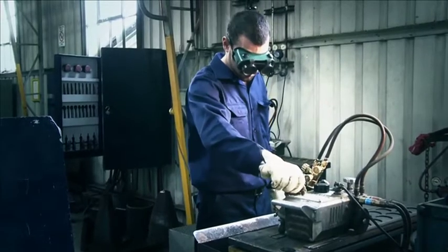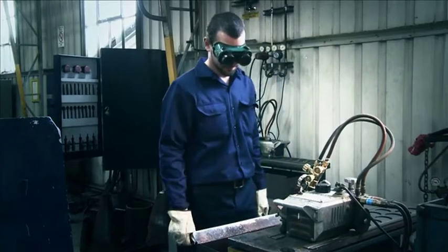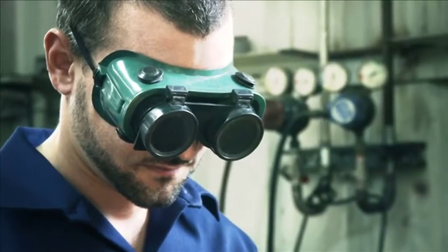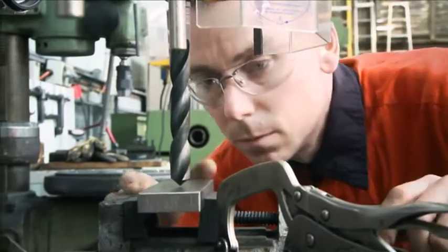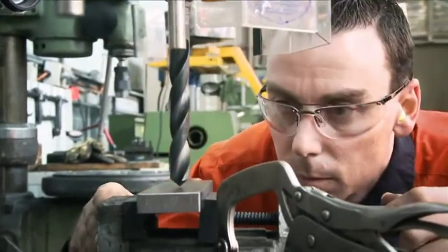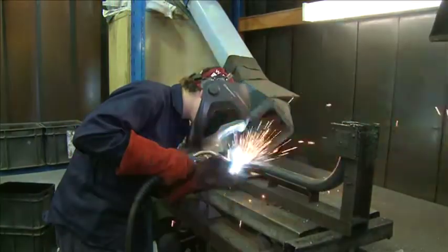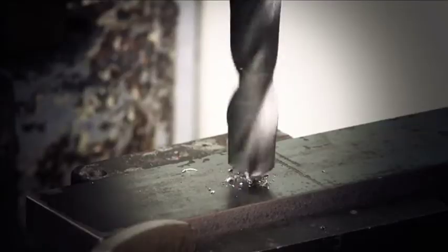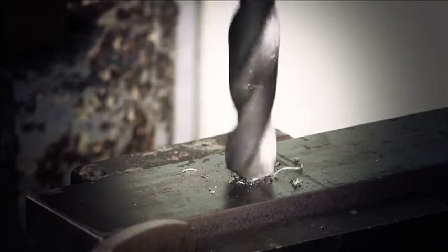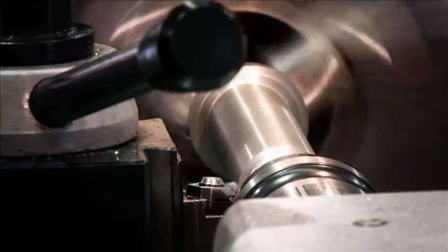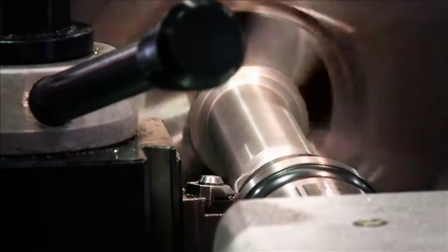You only get one set of eyes and they can't be replaced, but you can protect them. There are different types of eye protection for different jobs. Sometimes you'll need a full face shield instead of goggles, depending on whether you're cutting, grinding or drilling, for instance. Swarf can fly up at high speed and could lodge in your hair and clothing.